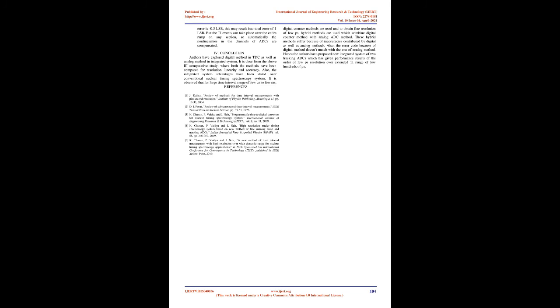In the analog method, the ADCs used for the digitization process play a crucial role in defining the nonlinearity of this conversion process. ADCs used in nuclear timing spectroscopy systems are preferred to be the ones which have low DNL error. INL error results in a spectrum peak shift which doesn't affect the TI measurement. But DNL error can result in TI measurement inaccuracy. So conventionally ADCs like the Wilkinson ADC are preferred for nuclear applications, which has low DNL error, but it has a large conversion time. Thus, the event rate gets limited for the system.